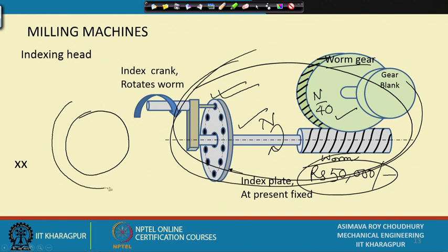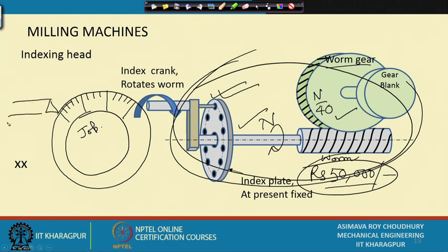I can buy a watch dial. How much would a watch dial cost? Nowadays wall clocks are quite inexpensive, and you can have this one for say 100 rupees. Just imagine 50,000 rupees and 100 rupees. I stick it to this job of mine. So, my job is having this watch dial connected to it, and I put a steady pointer here which does not shift from its position, and someone says, can you rotate the job by 60 degrees?